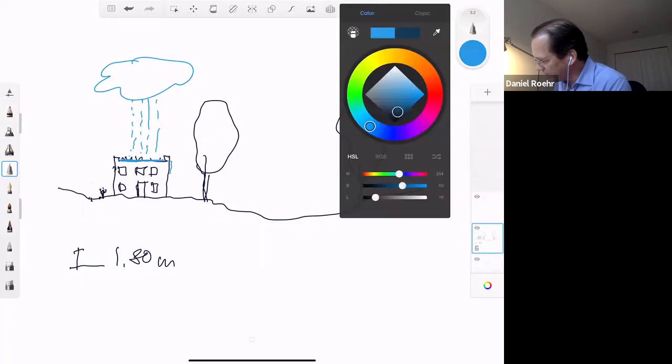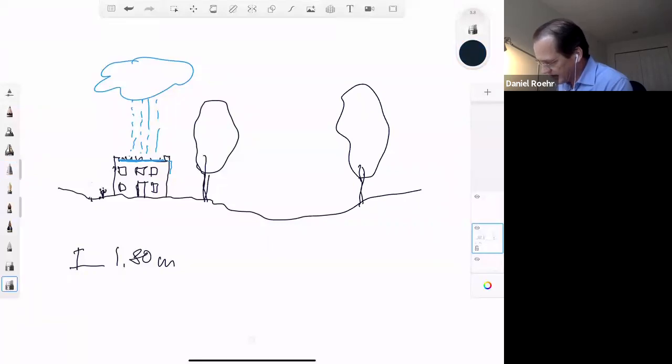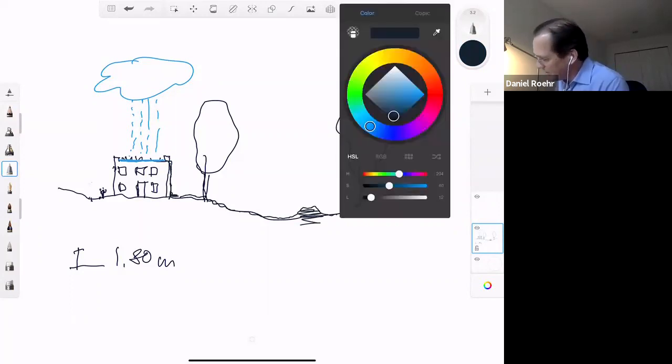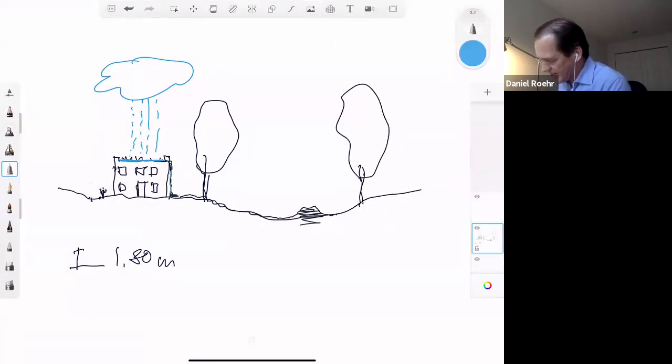Well, again, you need to switch to black, really black, go back to the little eraser, and then put in a downspout, okay? And that downspout doesn't go into the soil, it goes here. And then there's a little runnel, and maybe we can create some kind of dike system. We grade this a little bit here. And then the water, now saturated, will run down the runnel into this beautiful swale system where it will fill up. And obviously during that time it starts to drain into the ground, but at a certain amount it will flood over.